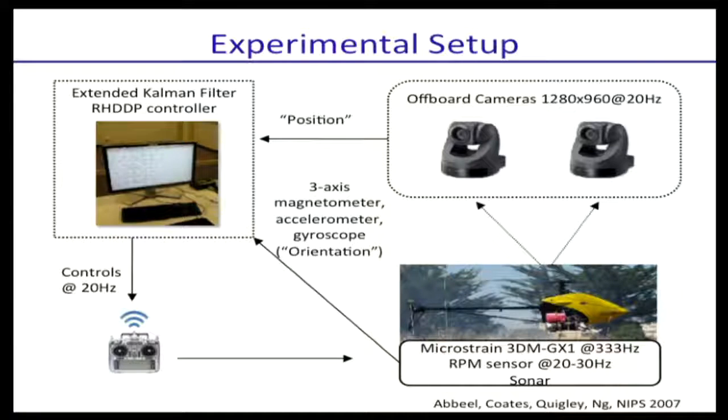The receding horizon part means that in this case, we plan for 20 time steps into the future. You execute just the first of the 20 time steps of controls, and then replan, so the model-predictive control approach. Key is to top it off with a value function at the end, because just looking 2 seconds ahead, well, we look 40 ticks ahead, 2 seconds, is not enough to do good control. You need to look further ahead. We can offline, from our iterative LQR differential dynamic programming runs, get quadratic value functions. You can use those as the end cost on your 2 second look-ahead to actually do the right thing in terms of anticipating the future.